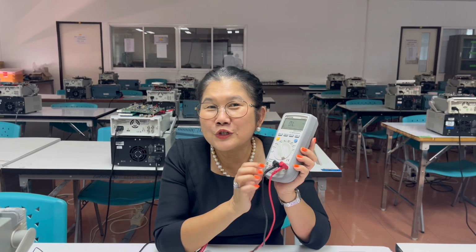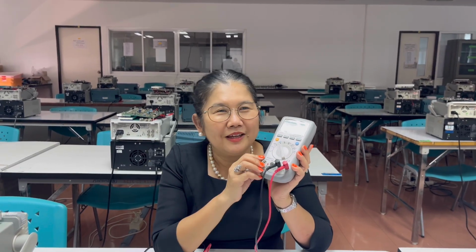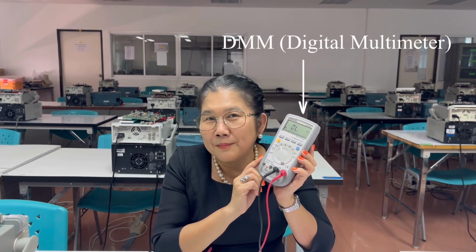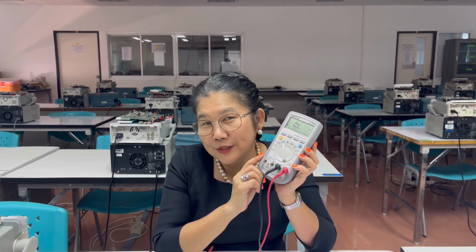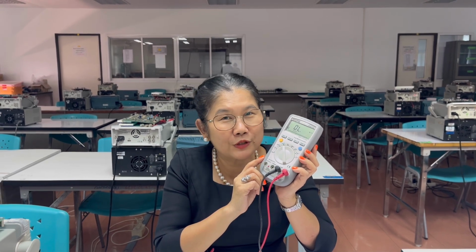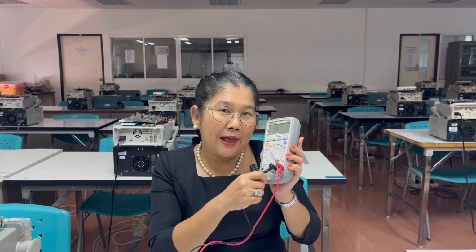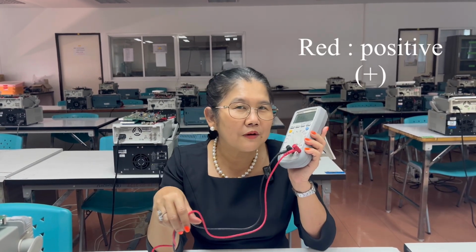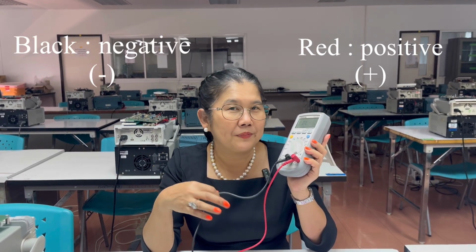So let me introduce to you some of the equipment that you need to use to play around with electric circuits. This is called the DMM, digital multimeter. It can act like a voltmeter, ammeter, and ohmmeter also. These are most of the things that we use it for. It has two probes, the red one and the black one. The red one we use to measure at the positive terminal of the voltage drop, and the black probe is for the negative terminal of the voltage drop in the circuit.